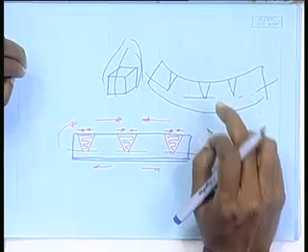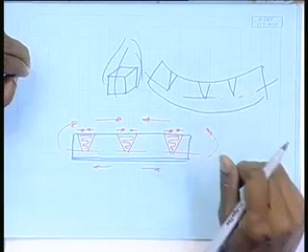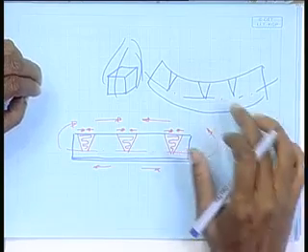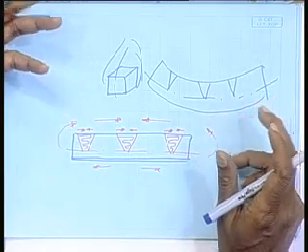So that is how frame bending can be done by line heating. But well, frame bending is much more easily done by frame bending machines, so that is not very much implemented as such. But for plate bending, this is probably the only option through which one can do automated bending using line heating.